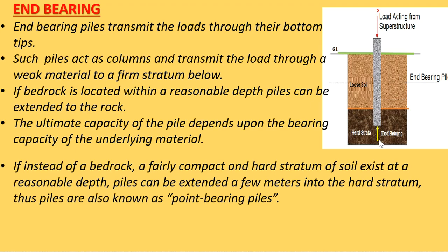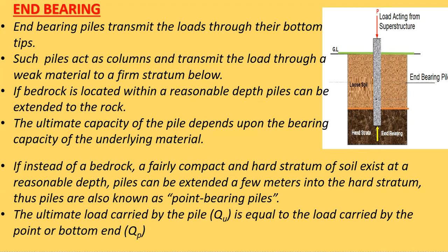If instead of a bedrock, a fairly compact and hard stratum of soil exists at a reasonable depth, piles can be extended a few meters into the hard stratum. Thus, such piles are also known as point-bearing piles. The ultimate load carried by the pile is equal to the load carried by the point or bottom end.